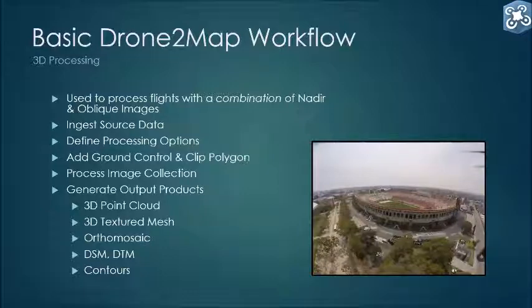This source data is then ingested, so to speak, within your Drone2Map application. You set parameters or define your data processing options, which depends on the level of quality needed for your output, as well as what outputs will be generated. You can also add ground control points and this will help to improve your accuracy. You'd have seen the mention of ground control points in the accuracy video that was shown before. You then run your processing to generate your outputs, and these can be 3D point cloud, 3D textured mesh, orthomosaics, DSM, DTM, as well as contours, and there are other options too.